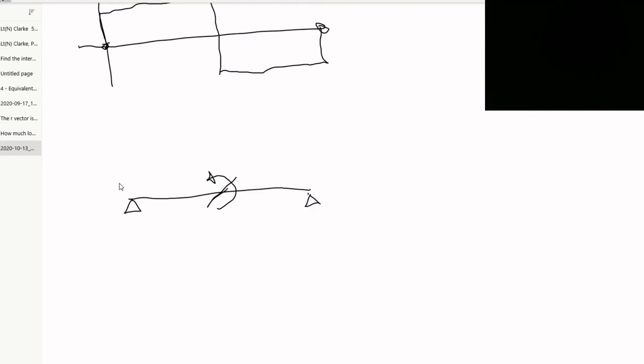I'm just going to draw the deformed shape here, generally exaggerated, of course, depending upon how stiff your beam is and how big the magnitude is. But we're going to get a deformed shape. It needs to bend back down here, and this one needs to bend back like this.